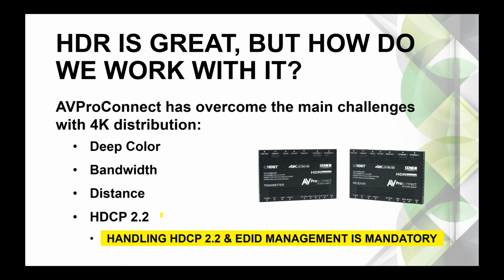But the components need to pass deep color, high bandwidth, distance, obviously HDCP 2.2, that's your copy protection, and then you need to have some pretty robust EDID management. We're going to talk a little bit about that in the next couple slides.